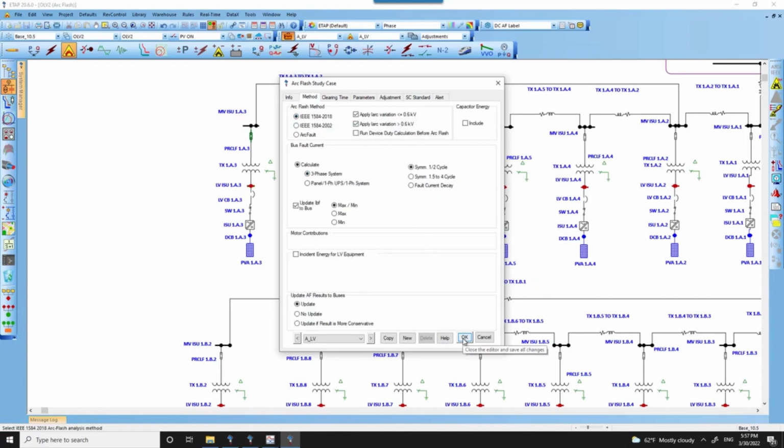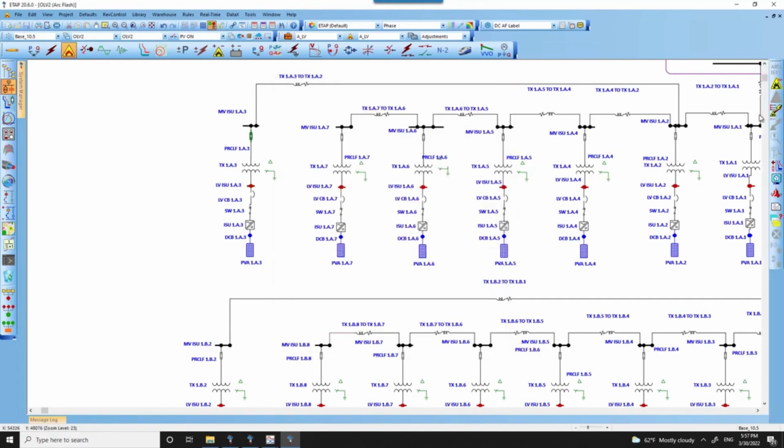Although the protection seems pretty solid with respect to the short circuit current, the non-linearity of the arcing current caused a reduction in the arc current and changed the entire trip time of that particular fuse, which resulted in a very high incident energy. So the original setting given to us, based on the calculation performed, started with a higher clearing time on the low voltage circuit breaker that is fed from the inverter.